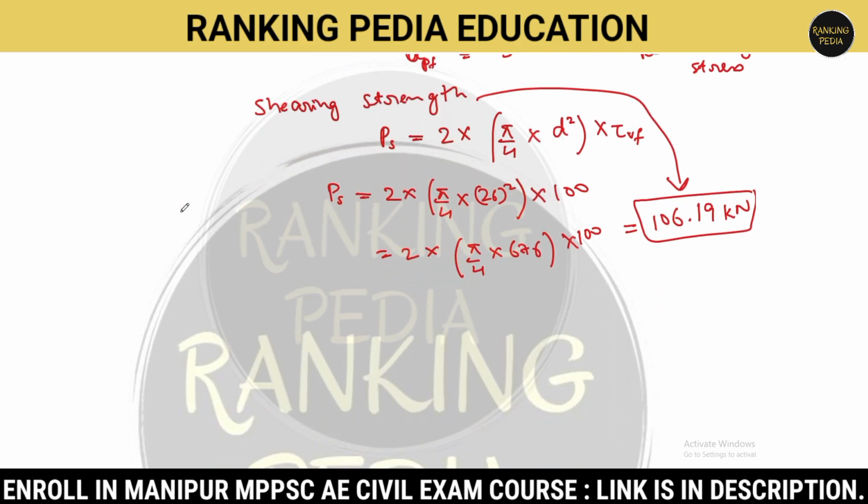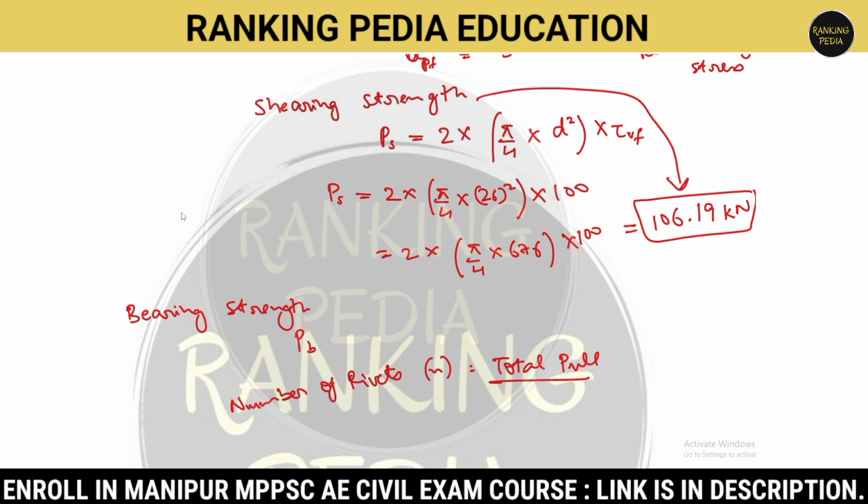Now what will we be calculating? We will be calculating bearing strength. Bearing strength will be denoted by PB. Okay. Now the fourth one is, we have to calculate the number of rivets. Also find out the number of rivets, which will be denoted by small n, and it is total pull by a rivet value.